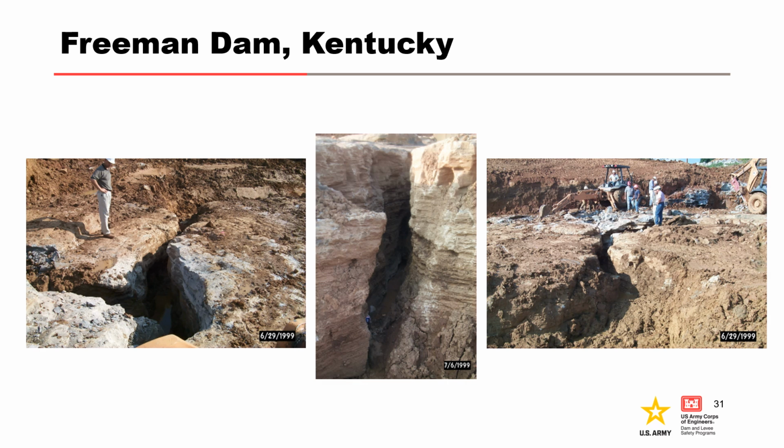Imagine water coming up during a high pool event, unraveling some of the overlying clay core, and removing soil particles as the water level receded. These karst features did not daylight at the downstream toe, and therefore no dirty water was ever observed at the site.